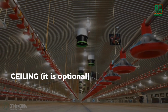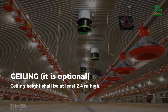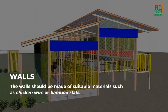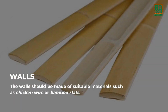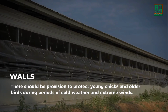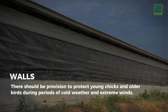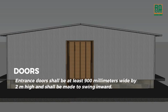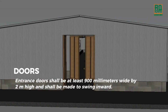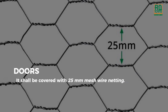Ceiling. Optional. Ceiling height shall be at least 2.4 meters high. Walls. The walls should be made of suitable materials such as chicken wire or bamboo slats. There should be provision to protect young chicks and older birds during periods of cold weather and extreme winds. Doors. Entrance doors shall be at least 900 mm wide by 2 meters high and shall be made to swing inward. It shall be covered with 25 mm mesh wire netting.